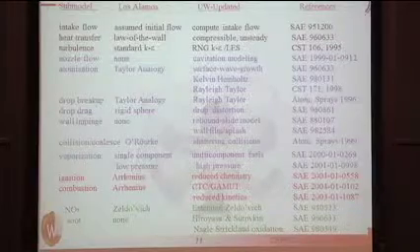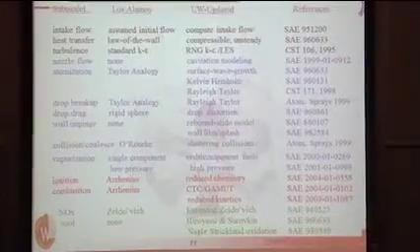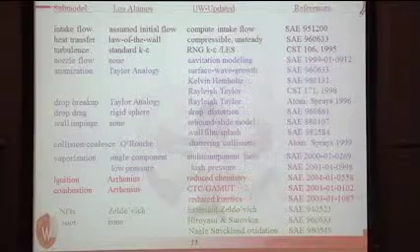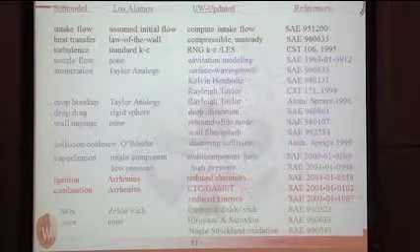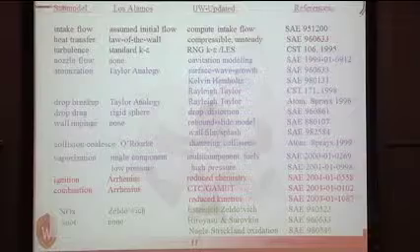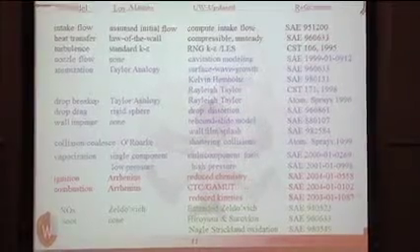The heat transfer model, in most CFD applications, you'll see the law of the wall used. Remember I mentioned that the boundary layers are very thin in an engine. 100 microns is a typical thickness. Again, that's much smaller than your 1 millimeter mesh, so you have to use a submodel. Law of the wall would be a candidate model. However, in an engine, the flows are compressible and unsteady, so we have introduced an improvement to the heat transfer model that takes into account those factors, and I'll talk about that.